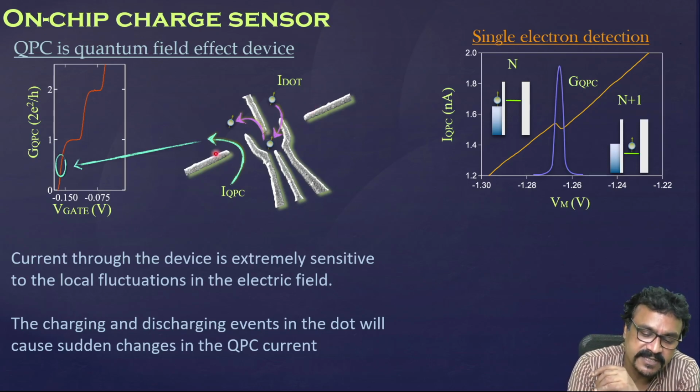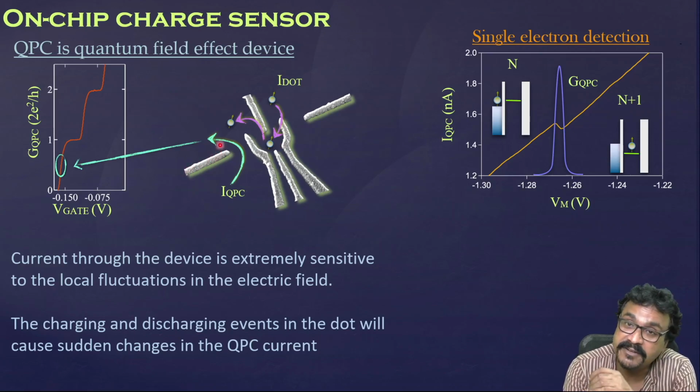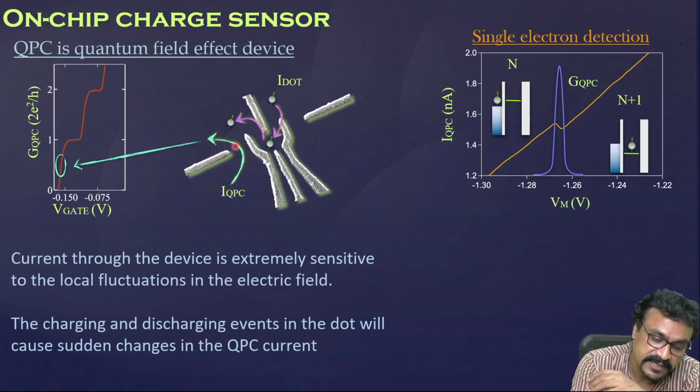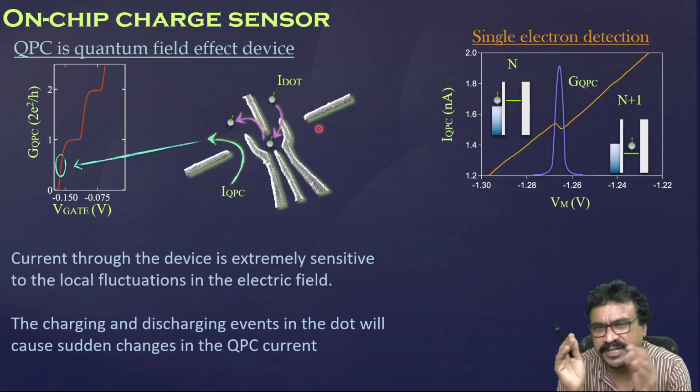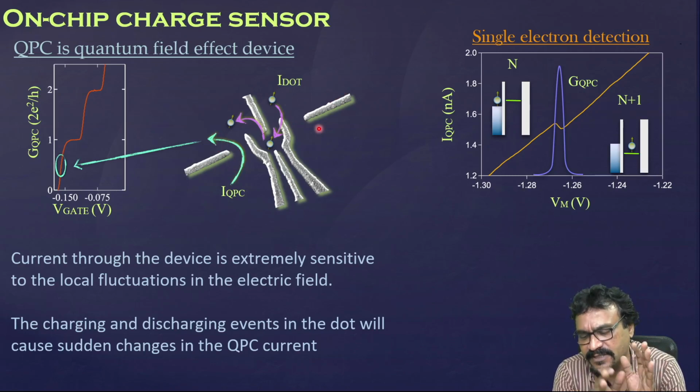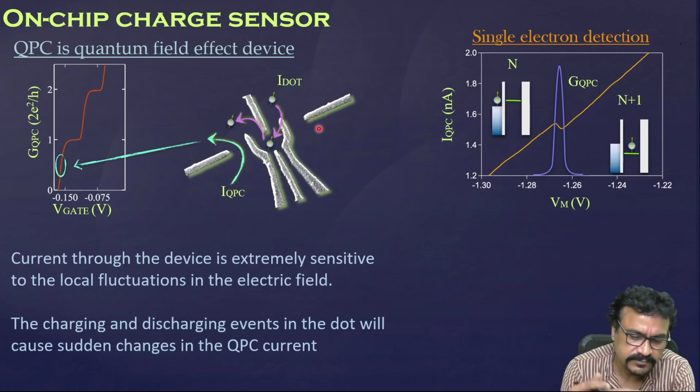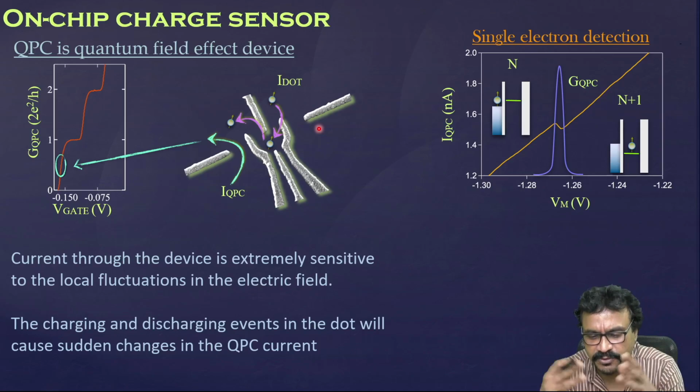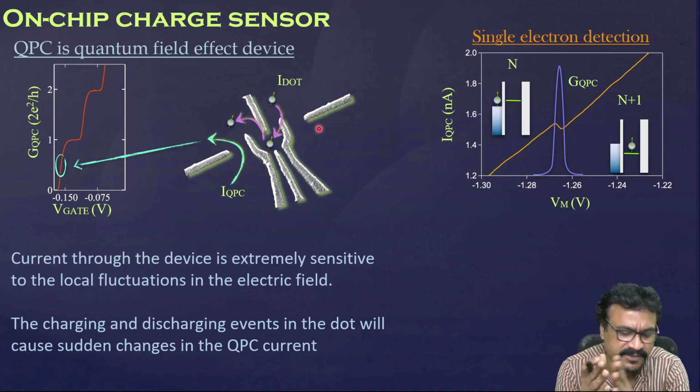But these two gates do not have anything directly to do with that confinement. What happens is, when you apply negative voltages to this gate, you also will create a thin channel this side and another channel on the other side. But you need only one channel to sense, that is the fact. You can have both if you want to do some specific measurement, but one is sufficient.